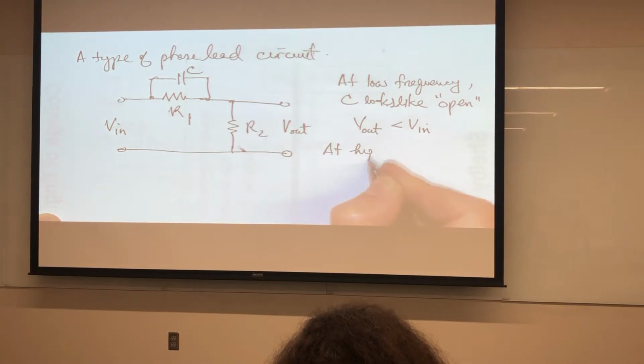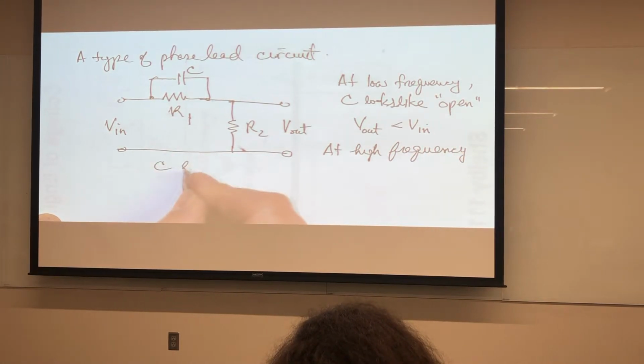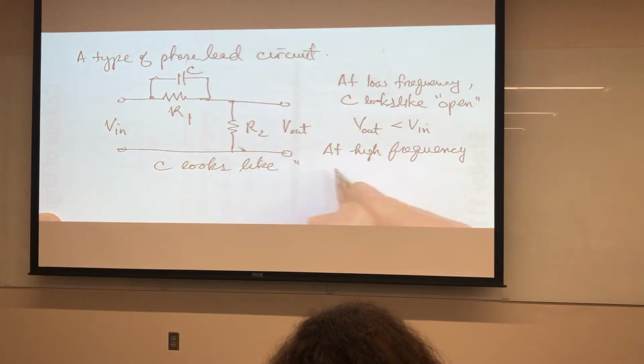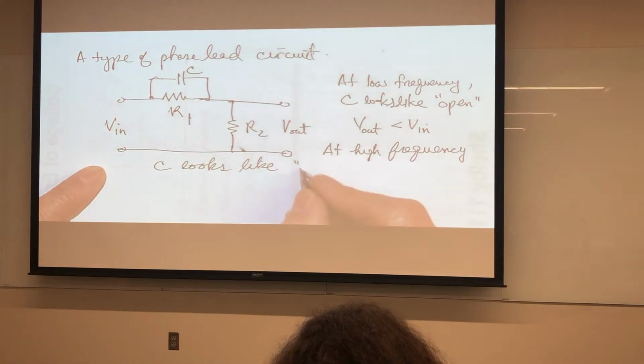At high frequency, what does C look like? This would be the opposite of an open. It looks like a short. That's what we remember from circuit analysis: capacitors are shorts at high frequency.